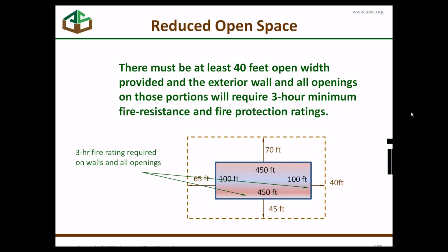If it's just required to be rated by the construction type, the A, so to speak, then you have the rating required, but the openings are unlimited and not required to be protected. So that applies to type B as well. You have type 3B, which is a type 3 building with no particular fire ratings. Type 3A is a type 3 building that's 1 hour rated throughout. And I think later on in your presentation you're going to get into table 601 where it talks about the fire resistance ratings of the elements. I will show that table. Yeah. Right.